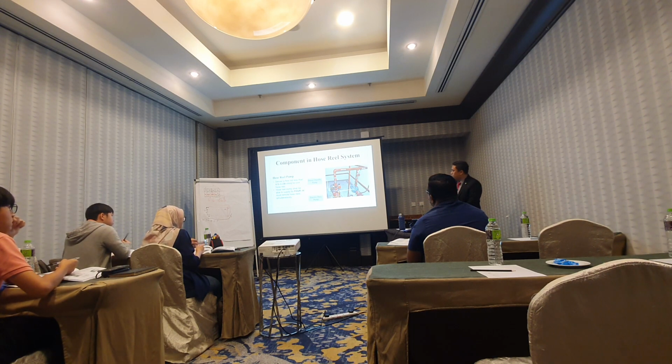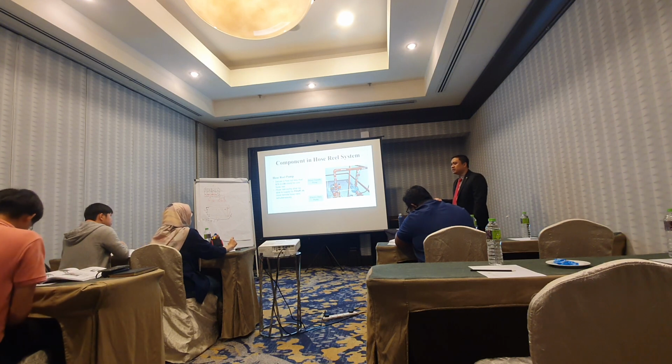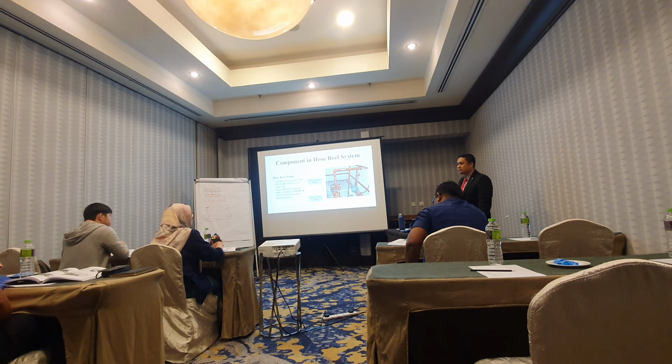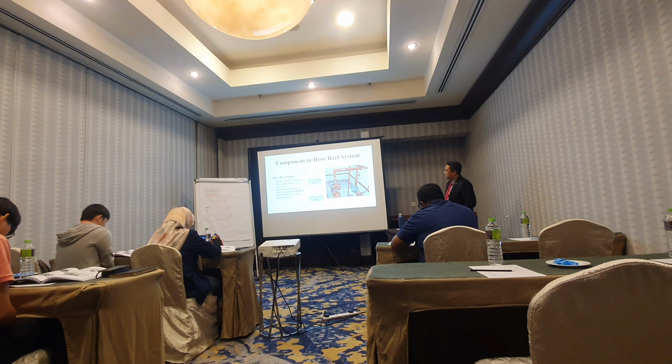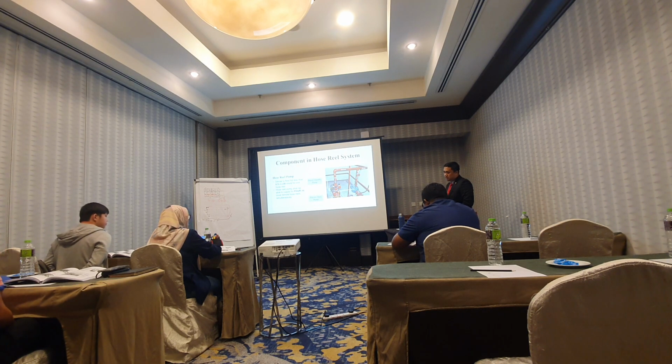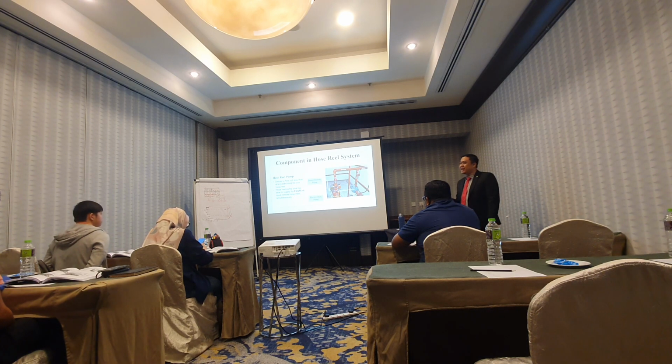So from this calculation kita tahu 30 liter per minute, you times by 60, how much do you get? 30 liter times 60, 60 minit, 1 jam. Then times 4, 7,200. That is where the maximum capacity of the hose reel is there.